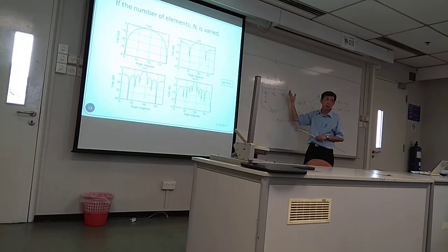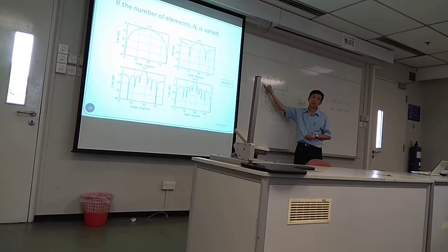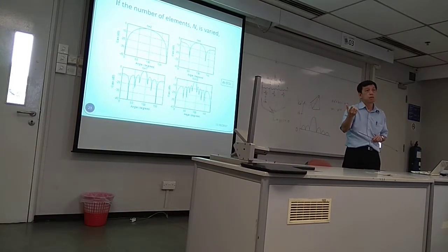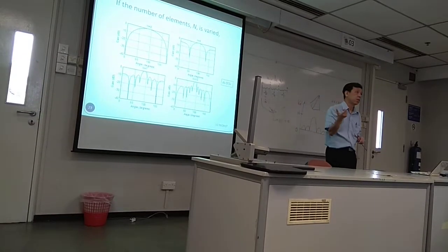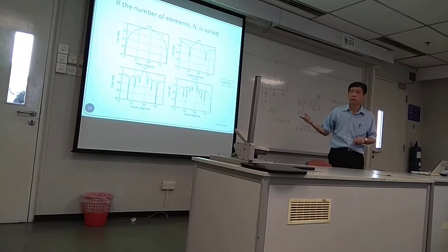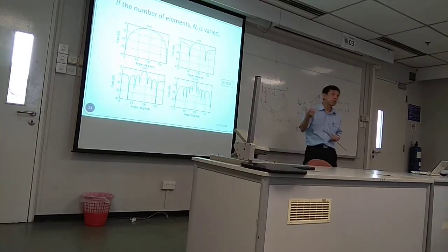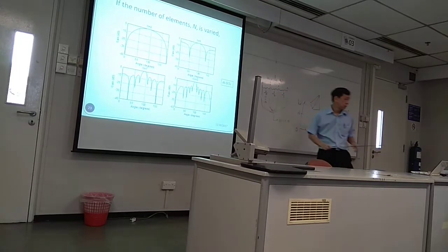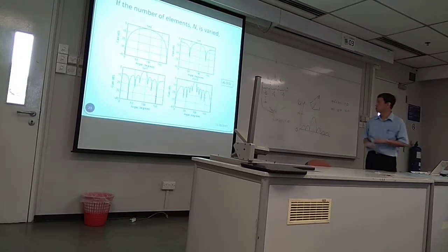In terms of FIR filtering, what do you have? If this is your sampling interval, and if your sampling rate is 2 times your signal frequency, then the sampling interval corresponds to what? Well, the phase shift is 180 degrees. Exactly the same thing. And you can actually see this as a kind of FIR filter, but in physical space.